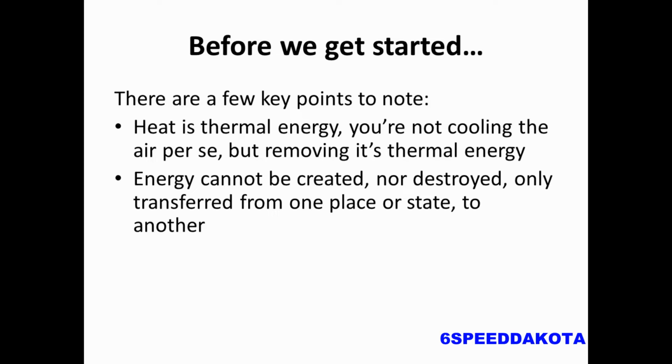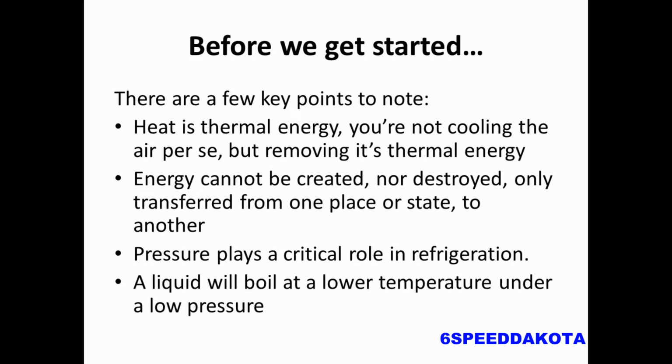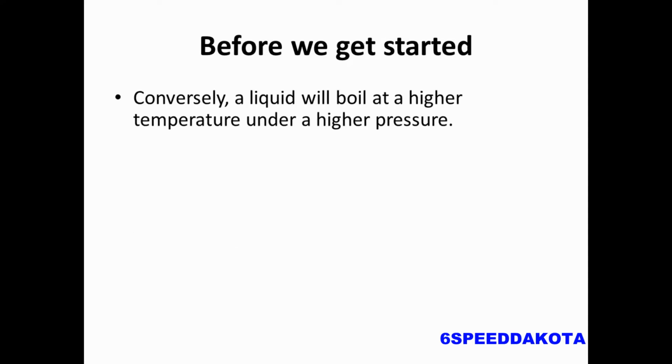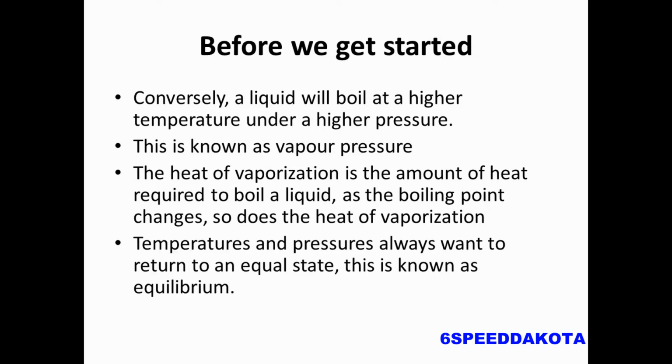Energy is not created nor destroyed, but it is transferred from one place or state to another. Pressure plays a very critical role in refrigeration. A liquid will boil at a low temperature under a low pressure, or even a vacuum. We'll get into that a little bit later too. On the other side, a liquid will actually boil at a higher temperature under a higher pressure. This is known as the vapor pressure. The heat of vaporization is the amount of heat required to boil a liquid. As the boiling point changes, so does the heat of vaporization.